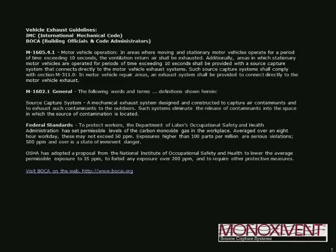And then below that, source capture system: a mechanical exhaust system designed and constructed to capture air contaminants and exhaust such contaminants to the outdoors. Again, the whole goal of this is to make sure that we're preventing breathing zones from being contaminated. Be sure to check, these are national or federal codes, be sure to check all your local codes as well to make sure that you're in compliance.